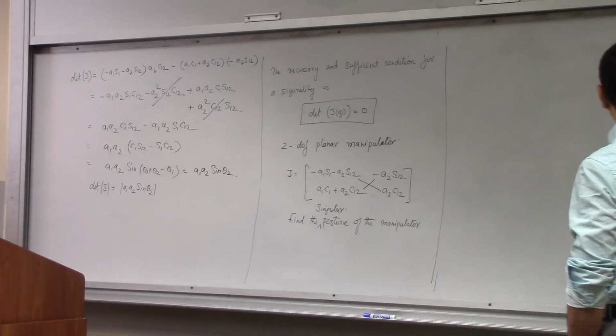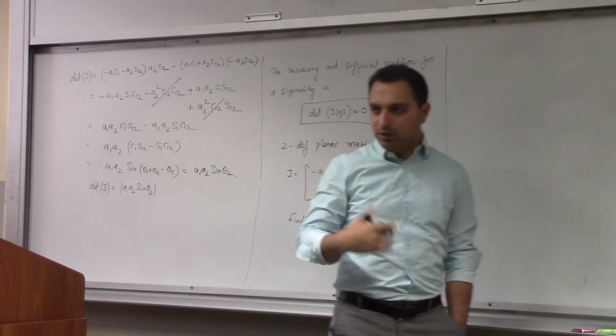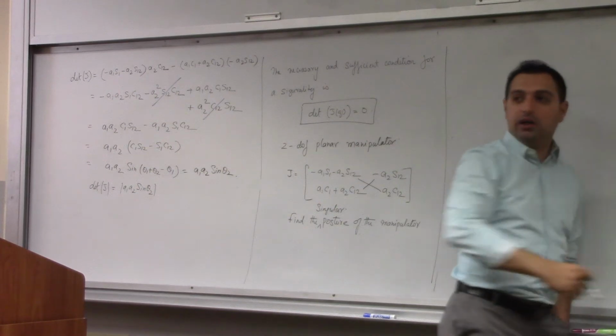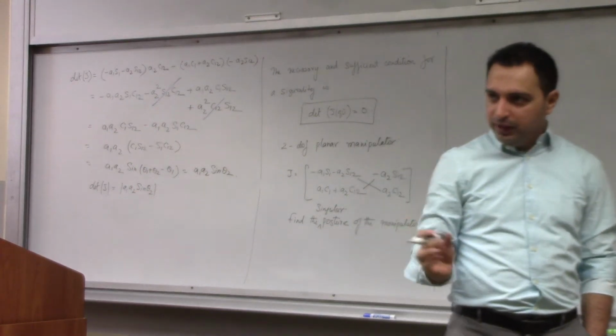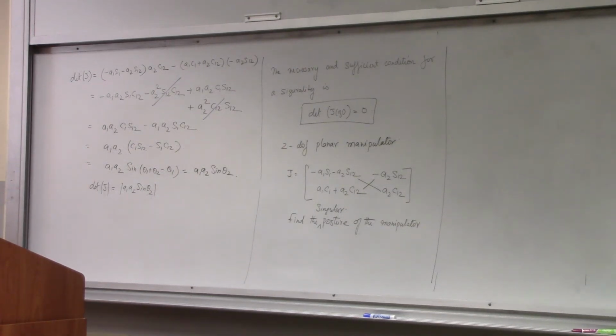If you are in a boundary condition like this, it is a simple thing to understand. You can visually tell that you cannot move any further here. But if it's a high degree of freedom manipulator, or if there are joint limitations, in this case you assume that theta 1 is completely revolute, which is from 0 to 360. That does not happen in practice.